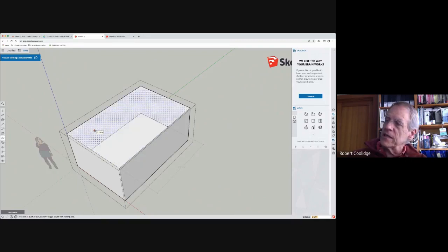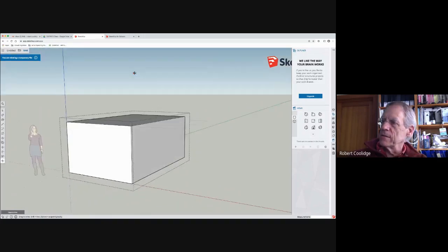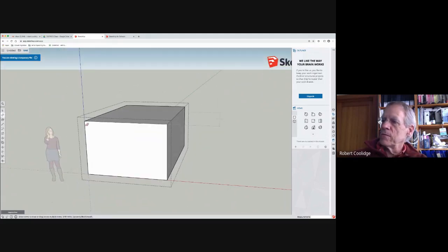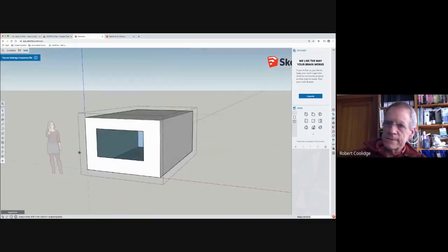This is inferencing, so it has perfectly aligned it, and I can erase these lines and restore it back to what it was. Let's draw a rectangle on the end here like this. Now the lines don't cross other lines, but it still created two different surfaces. It really did break the surface. You can delete that surface and you have a box with a hole in it.